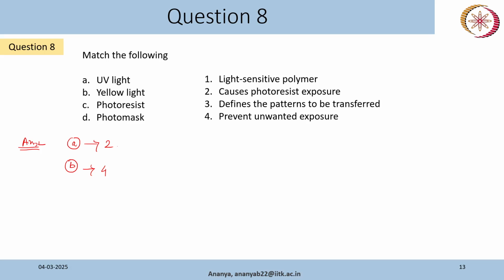Nowadays we have this habit of using phones all the time. It is not a good idea to use them there, because the light from our phone is white light, and if we use the torch that will also expose the photoresist. We don't want that. We use only yellow light in the litho room.